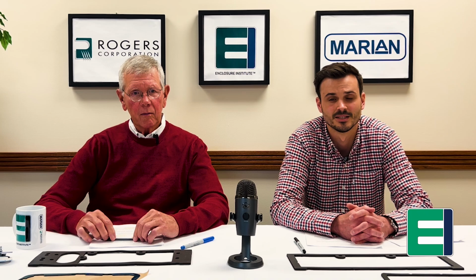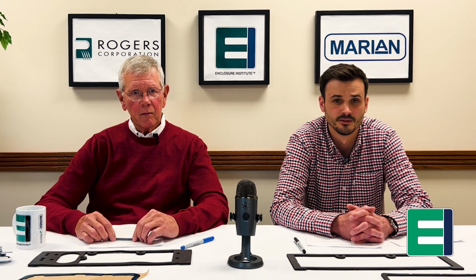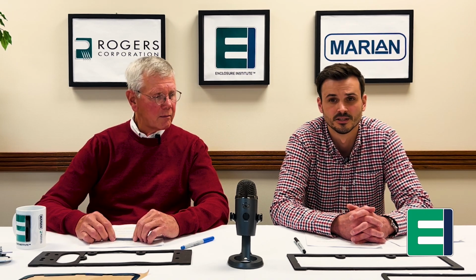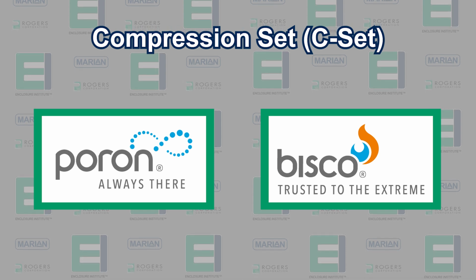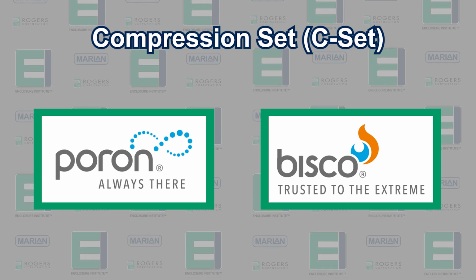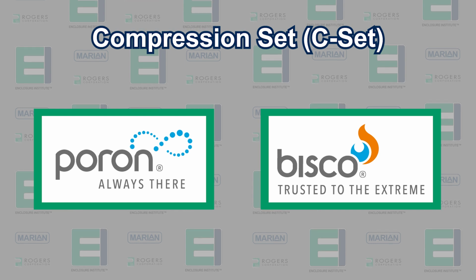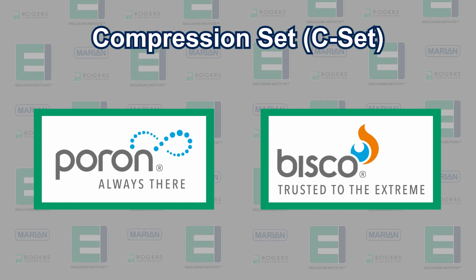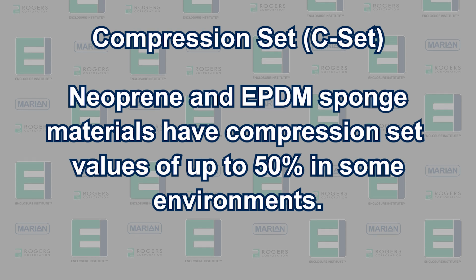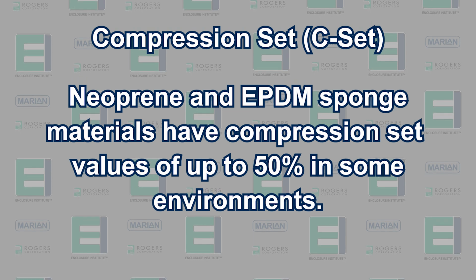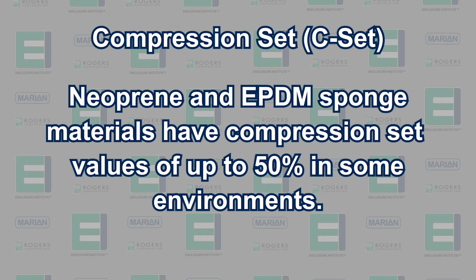But if such failure is critical to your device's performance, then a foam material with exceptional compression set resistance should be chosen. Materials with superior compression set resistance, such as PORON polyurethane or BISCO silicone, maintain their CFD and resist stress relaxation more than any other foam materials. These materials have compression set values of 5% or less, even in demanding environments. By comparison, neoprene and EPDM sponge materials have compression set values of up to 50% in some environments.